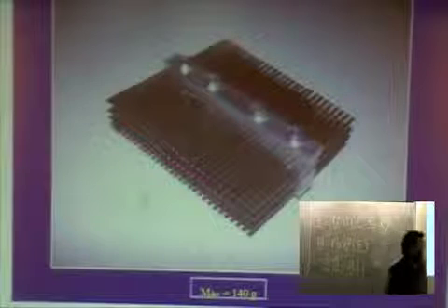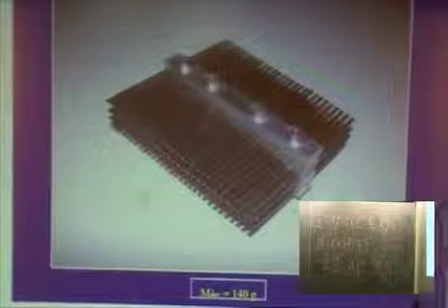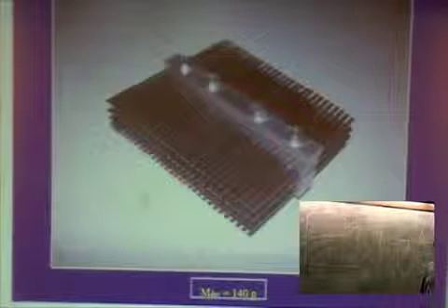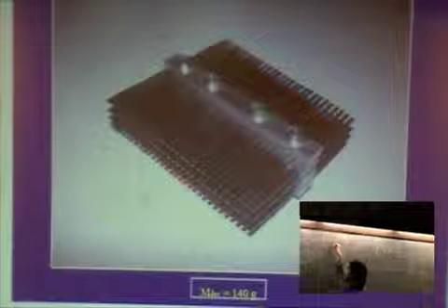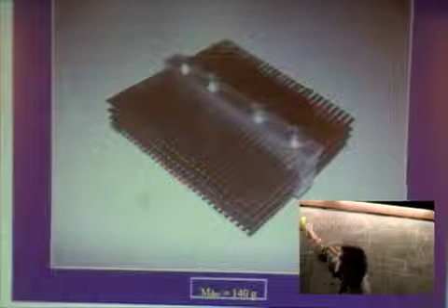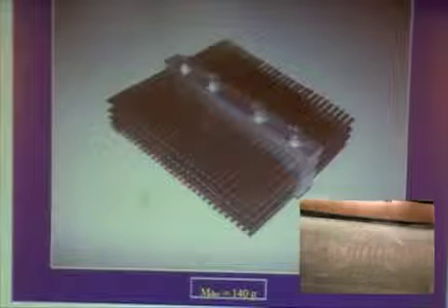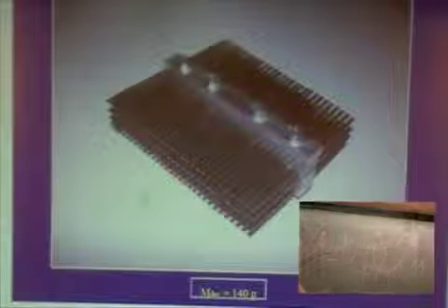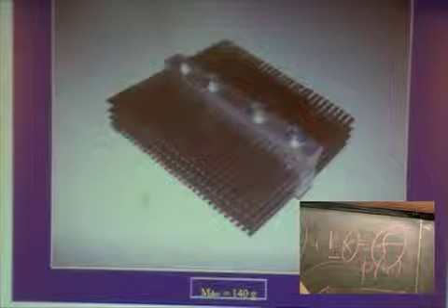So we are exciting a system that we say has this equation. I know the force that I'm imposing to the system. I know the displacement because I can measure it. I know the mass. I know the spring constant. Identify C, but just on the basis of experiments.